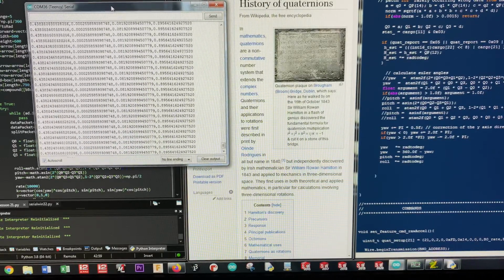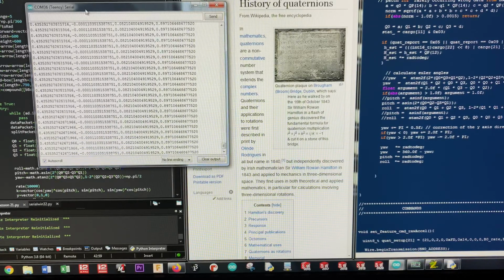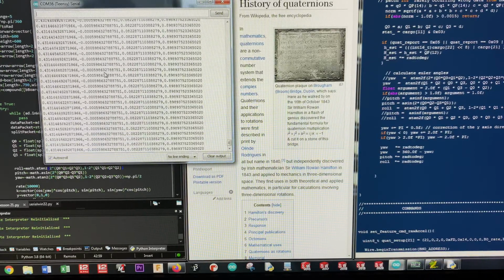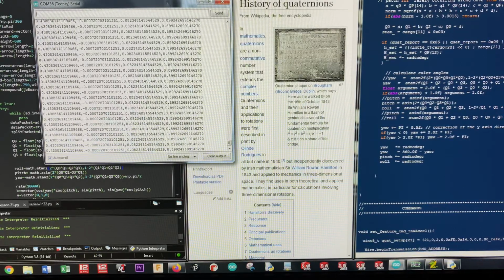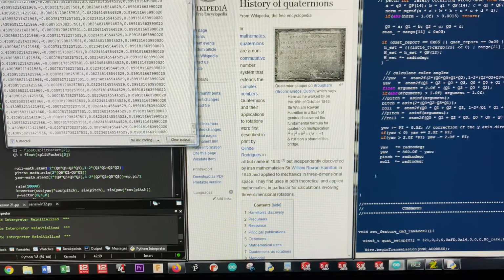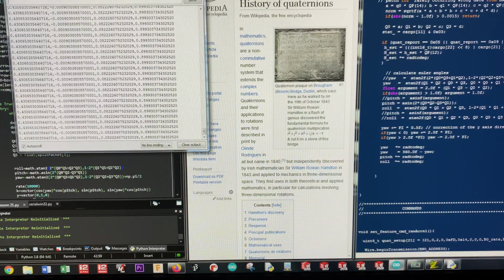chip on this board that does a lot of the heavy lifting as far as math. So for quaternions, it spits out this value for you. And what can you do with this value? What do you do with quaternions? You can take a quaternion, and using Mr. Hamilton's math from the 1800s, you can calculate a pitch or a roll angle, and that is an Euler angle.